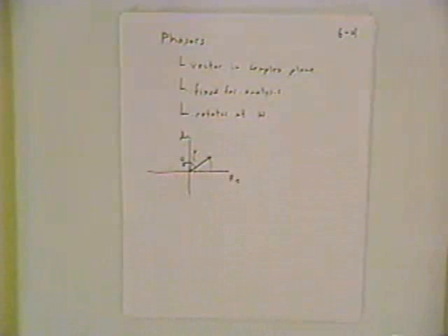And so in fact, if I look at my pen here as the phasor rotating, imagine that it's rotating around. Now I have to think through this. I want it to go counterclockwise as you're looking at it. So I'll go clockwise. And as this pen is rotating around and around, follow the tip of it. But I'm going to continue that rotation, but now I'm going to do it in a plane, so that now all you can see is the tip. And the tip is oscillating back and forth. If I just project the tip into space, it's going back and forth like this. It's tracing out a sinusoidal waveform in space.